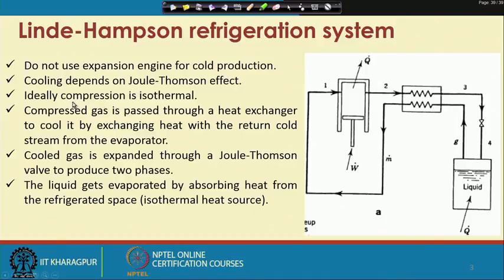Generally, the compression is done ideally as an isothermal process. As I said, this kind of compression may need multi-staging in practice, and when multi-staging is done, we also need intercoolers, aftercoolers, etc. to keep the temperature almost constant between the inlet and the outlet of the compressor. For the analysis, we will be considering all the compressors and other heat exchangers to be ideal.